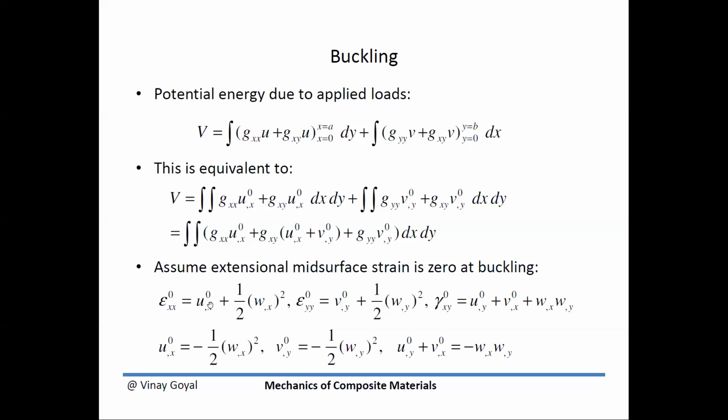And when we do that, you will quickly notice here that, and I'm actually keeping higher order nonlinear terms, from the strain deflection relationship. This is something you have not seen for a while, but I've made that conscious decision because to really predict buckling, you have to consider the higher order terms. And so this is exactly what I've done. Set this equal to zero, solve for u comma x superscript zero, and do the same thing here. So solve for this in terms of the rest of the stuff. Once I do that, I'm going to take this information and plug it back up here.